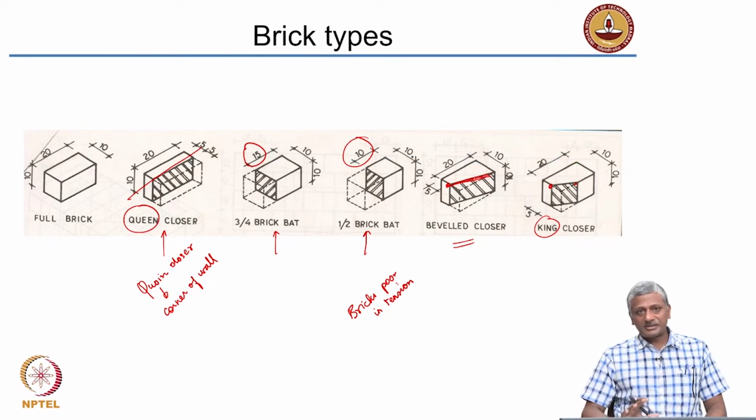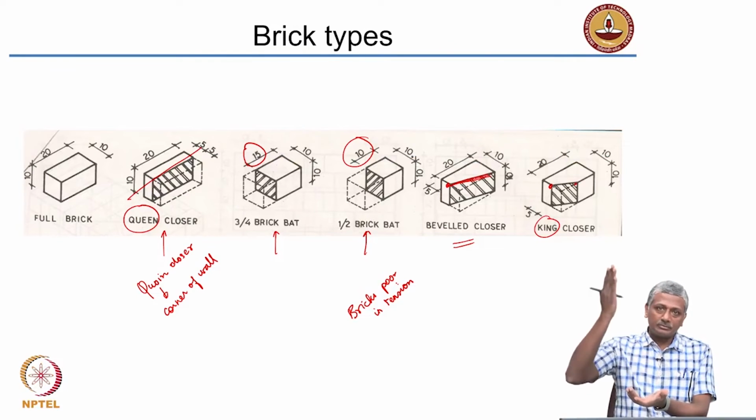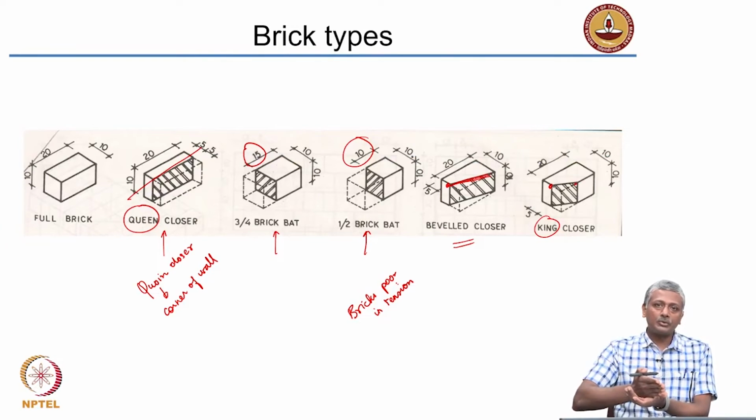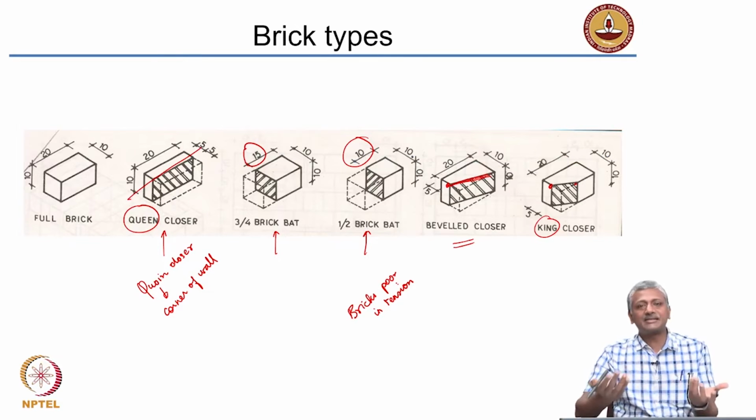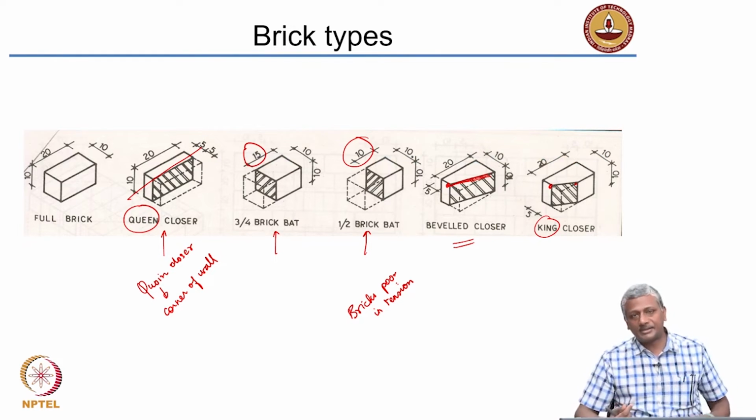As far as bricks are concerned, like stone or concrete, they are also very poor in tension. So, when you use a trowel to slice the brick, it slices easily because the edge of the trowel puts the brick into tension. So, it is able to fracture quite easily.